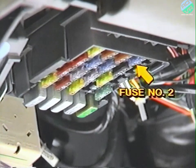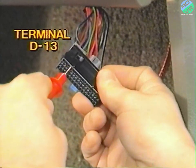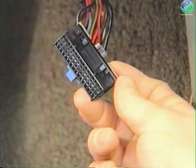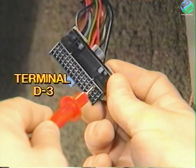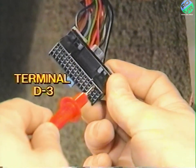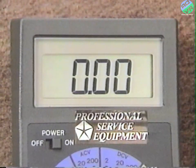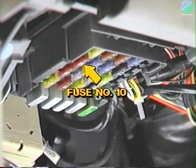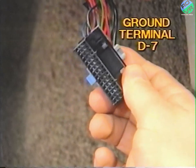If the fuse is intact, your next check should be at the ACM connector terminal D13. This is the battery voltage feed to the ACM. Now, with the ignition switch in run, also check for voltage at terminal D3 on the ACM connector. This is the ignition switch feed to the ACM. If there is no voltage at D3, check fuse 10 in the fuse panel and the circuit between fuse 10 and terminal D3. Next, check the ground for the ACM at D7.